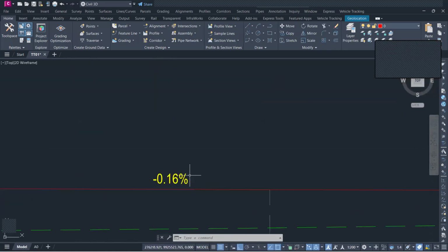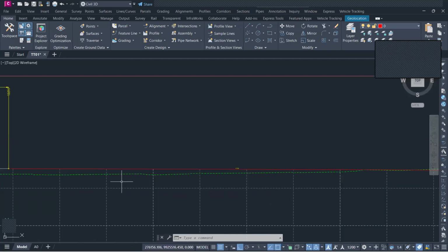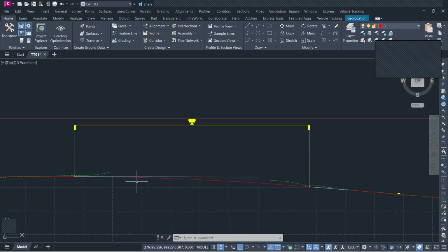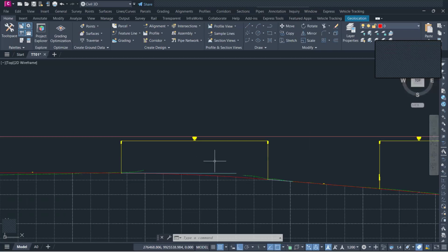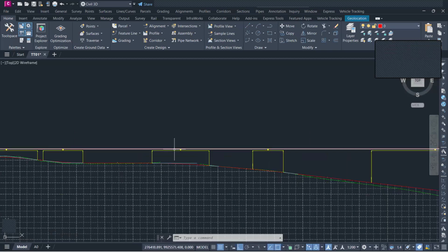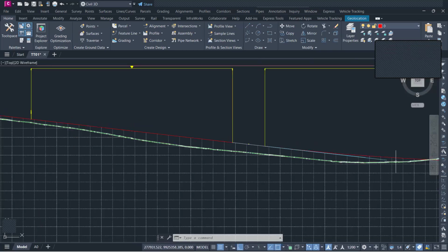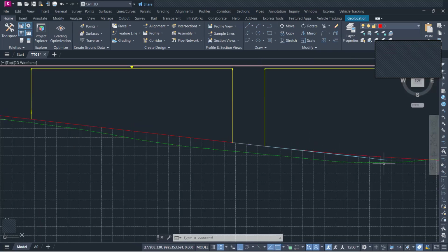So, for example, if you look at this design, we said that to control drainage, you use a gradient that is greater than 0.5, especially in cut sections. But of course, in fill sections, there is an exception. All the same, the rule of thumb is you should make sure that you don't have any gradient less than 0.5. So when we look at this design, this is, for example, a fill section.